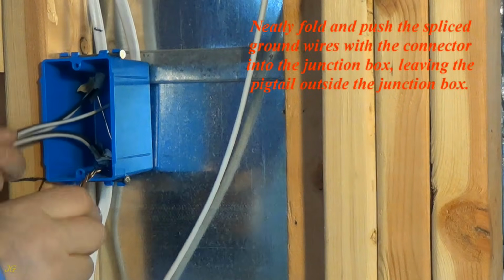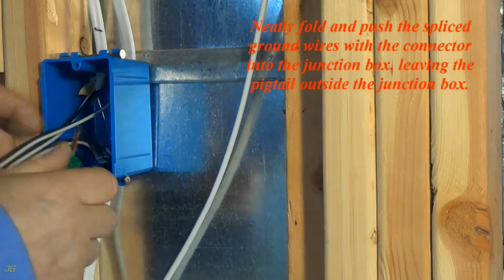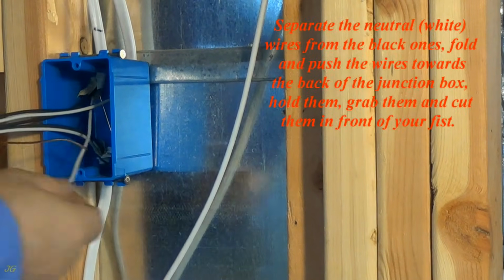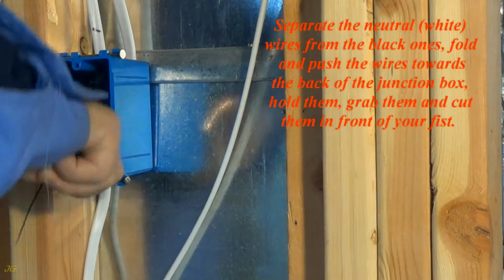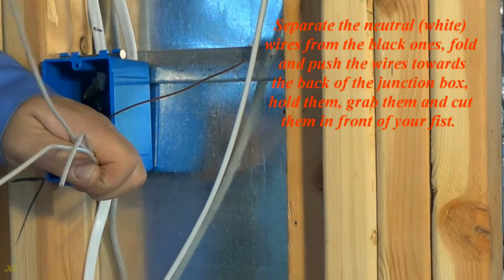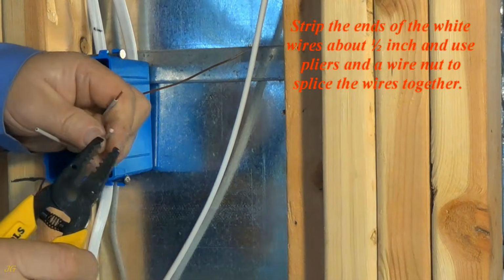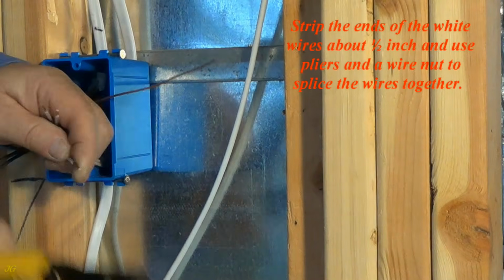Neatly fold and push the spliced ground wires with the connector into the junction box, leaving the pigtail outside the junction box. Separate the neutral, white, wires from the black ones. Fold and push the wires towards the back of the junction box. Hold them. Grab them and cut them in front of your fist. Strip the ends of the white wires about 1/2 inch and use pliers and a wire nut to splice the wires together.